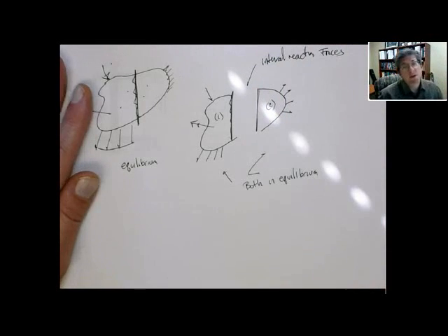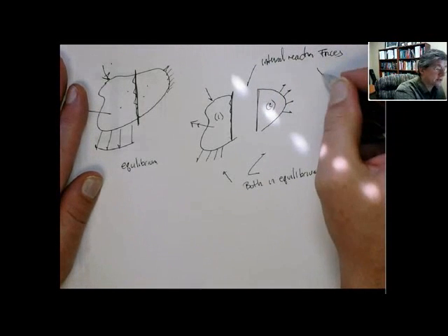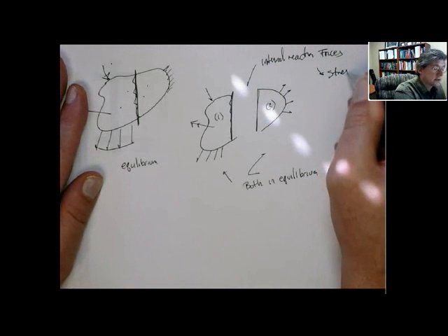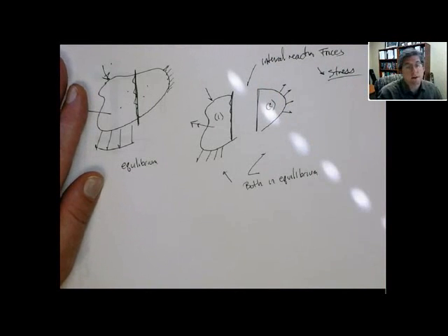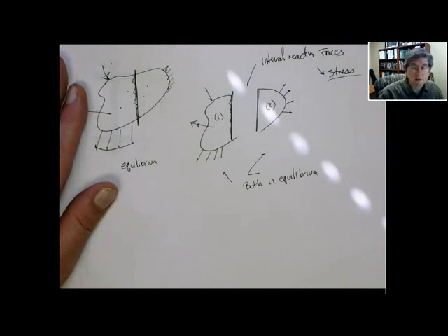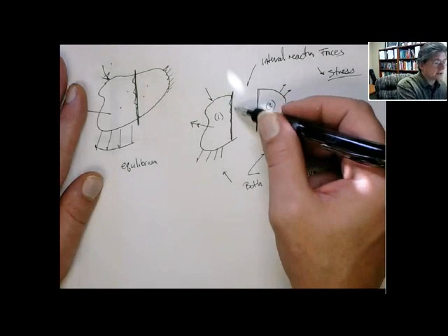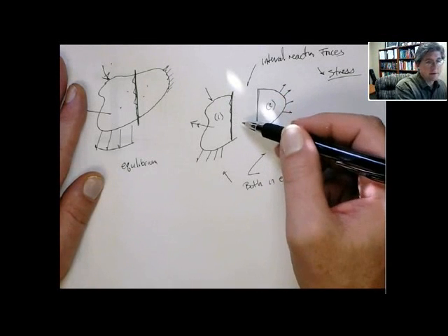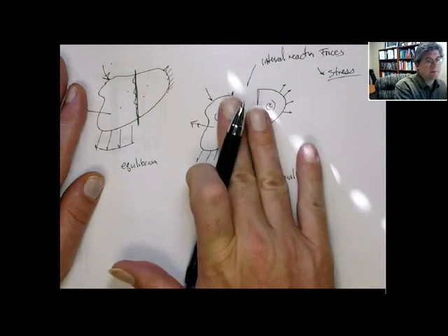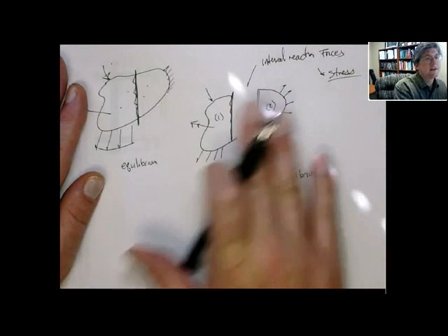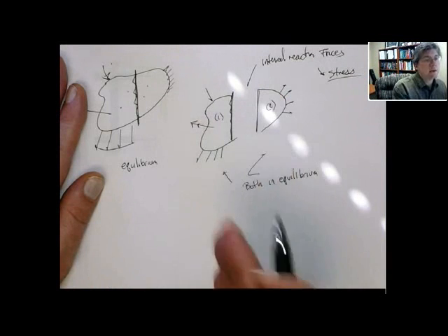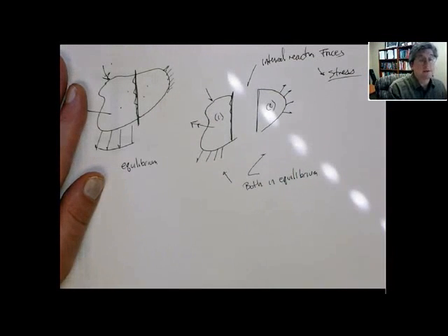Okay? These are the forces that are going to end up giving us stress, which we'll talk about later on. But that's a quantity of a lot of interest to us. So there's equal and opposite internal reaction forces on this. So the way you have to think of it is there exists some set of forces on body 1 that, if we pull this away, would exactly equal the forces that body 2 exerts on 1.